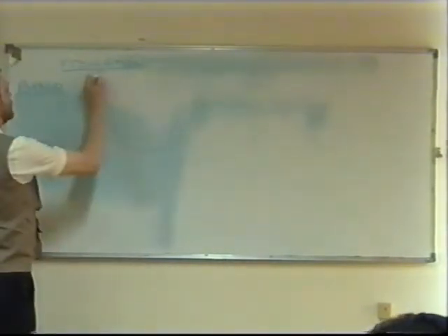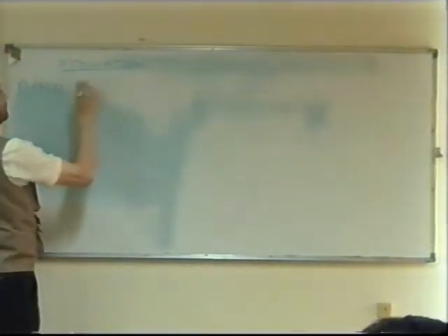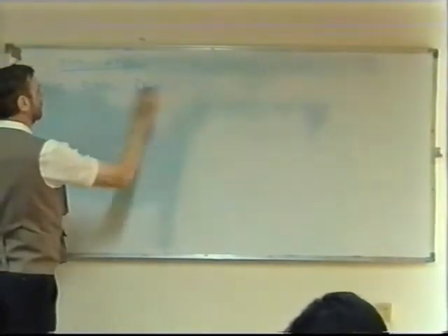We call these audio signals. Why do we call them audio? Small frequency. They're quite low frequency, but that's not the only reason. The reason for audio means that if they were sound waves, we'd be able to hear them. If you can hear it, it's audio. That's right. So the audio frequency range for telephones, we normally accept to be between 300 hertz and 3 kilohertz. That's right.